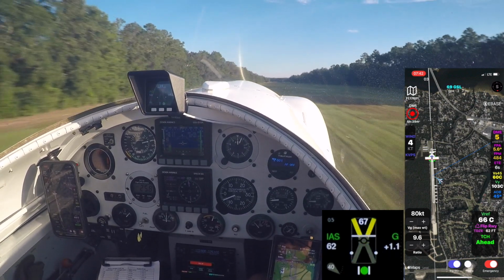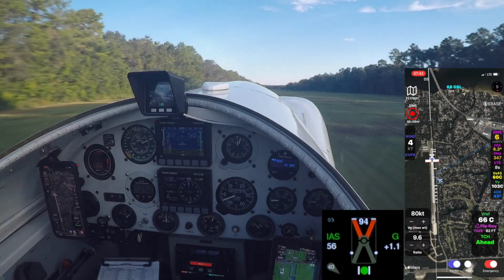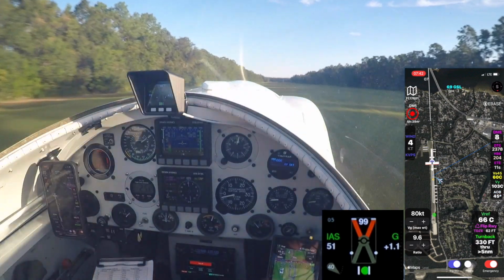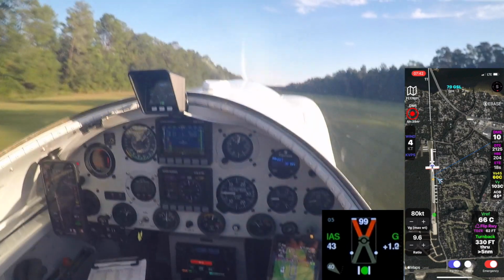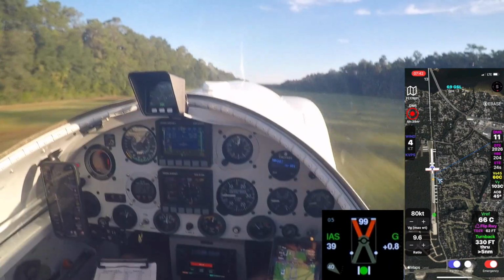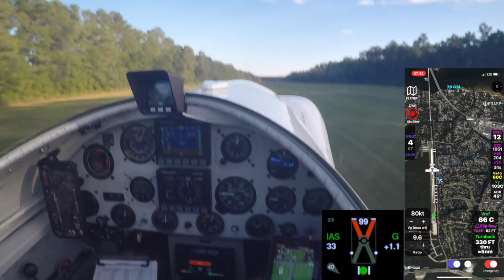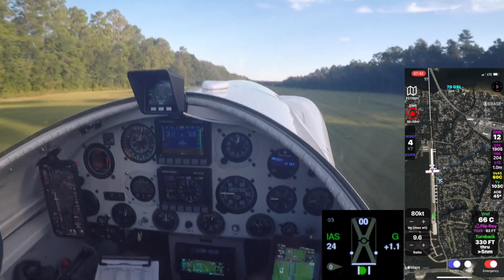And you can hear the airplane slowing down as we put her into three-point attitude. And now it's just a matter of rolling the wheels onto the ground. I can't carry too much energy if I'm on speed on approach. So it's always going to be a matter of just rounding out and touching down.